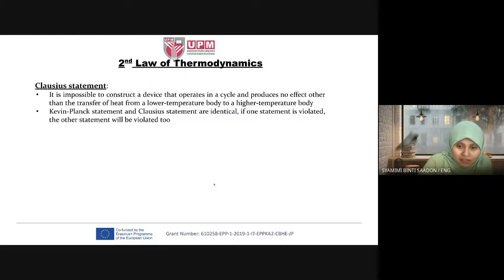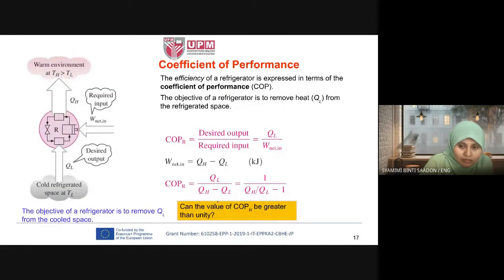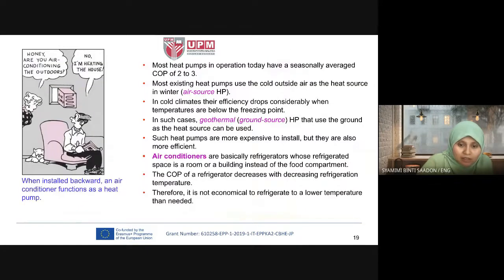The COP of a refrigerator decreases with decreasing refrigeration temperature. So if the refrigeration temperature decreases, the COP here decreases. Therefore it is not economical to refrigerate to a lower temperature than needed. So we have a certain peak value of temperature that we need to refrigerate our freezer.